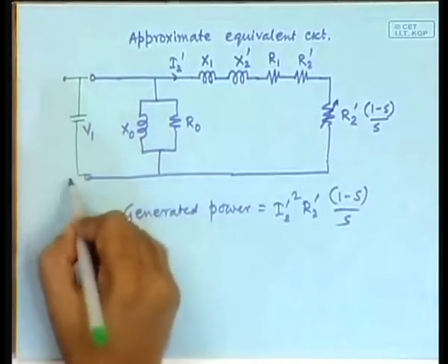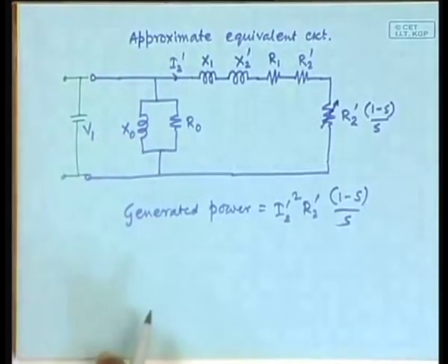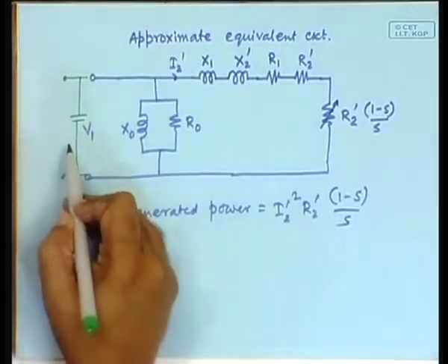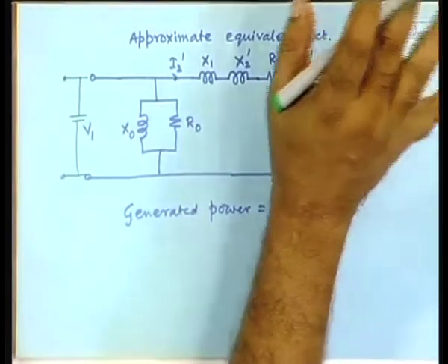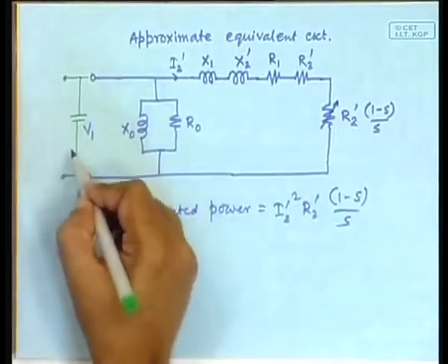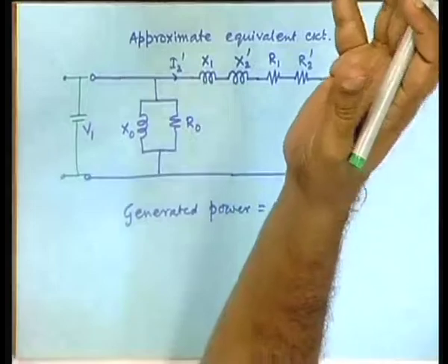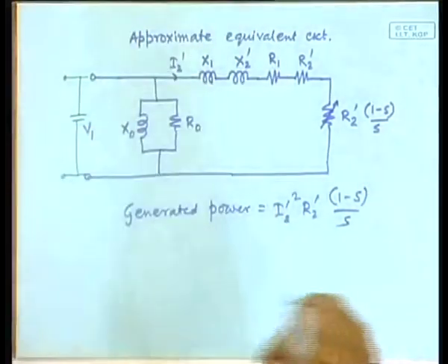And then it is a line. These are external capacitors, it is not really there inside the machine. Externally you apply or connect this capacitor. I have shown one, but this is actually a 3-phase machine. So a capacitor bank has to be connected either in delta or in star, finally supplying this reactive power into the system.